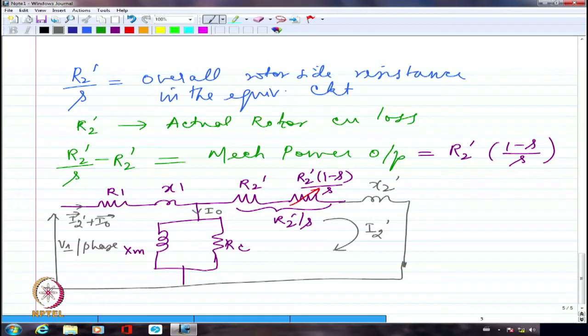So I will never ever have an induction motor work in unity power factor. I will never ever have an induction motor working on leading power factor. It is an inductive effect always. I will need that current no matter what to establish the flux. And if I am establishing a flux, it is inductive.